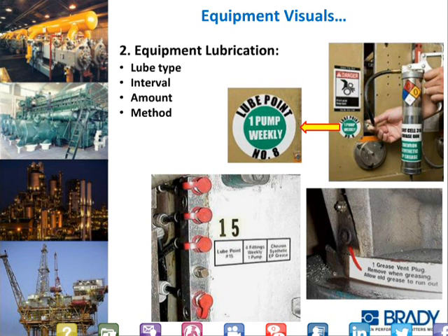So those grease caps do two things. One, protects the little check ball in there from getting contaminated or jammed or rusted open, but it also provides a color code. The label, and again, these are industrial hardened labels, the Brady labels from the label machine, tells me it's lube point 15, 4 fittings, weekly, 1 pump, with a Chevron synthetic EBP grease. The labels reinforce what's in the lubrication PMs, the lubrication route, the lubrication procedures. It's not designed to replace it. It reinforces, helps error-proof and mistake-proof.